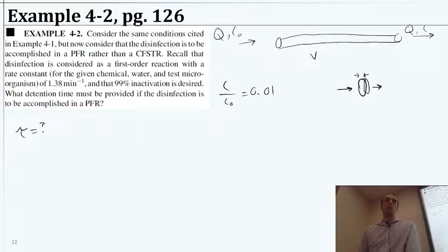That's one way to do it, and that's the steady state approach, because we could get the whole pipe in a steady state, and each little tiny reactor would be at steady state, well mixed within itself, and acting like a little CSTR. But we need an infinite number of those, so if we derive our mass balance for one of them as 1 over 1 plus tau k, we need to take that to the infinite power.